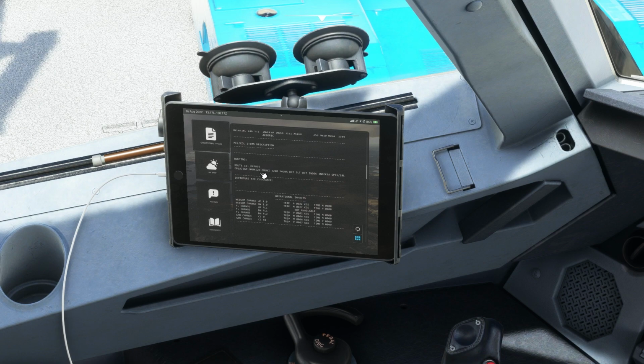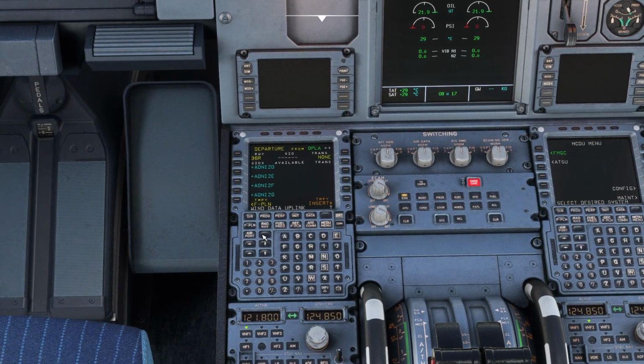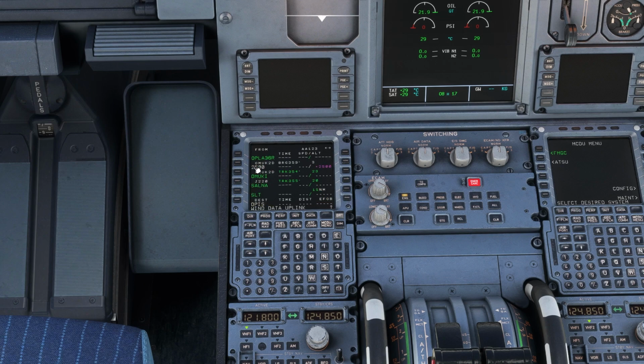As told you before, the route information is coming here. So from 36 right, I will be using SID to go to this waypoint OMUKI. So SID is OMUKI 2D. So I simply have to scroll by pressing this up button, and let's select 2D. So here it is, and temporary insert. So that's it. Now you can see that this OMUKI 2D information is also coming, and going to OMUKI and then J22 airway to Salna and then direct to Sialkot. So you can see in this flight plan the airways are coming over here in the white text, and in the green it's the waypoint.